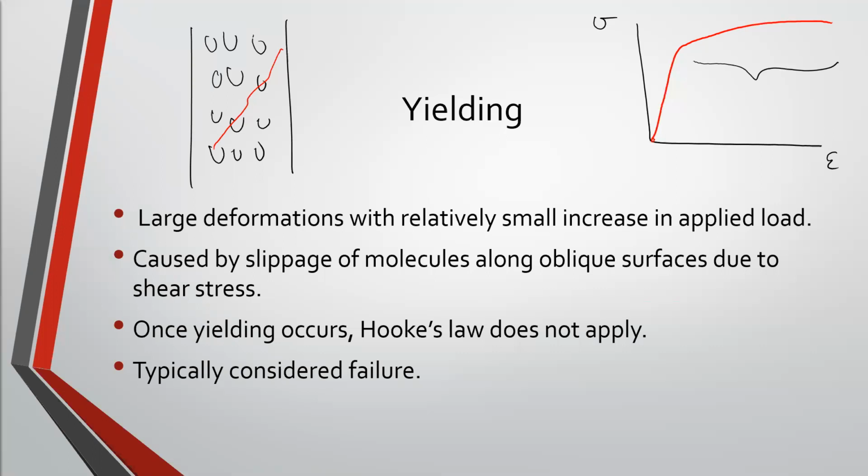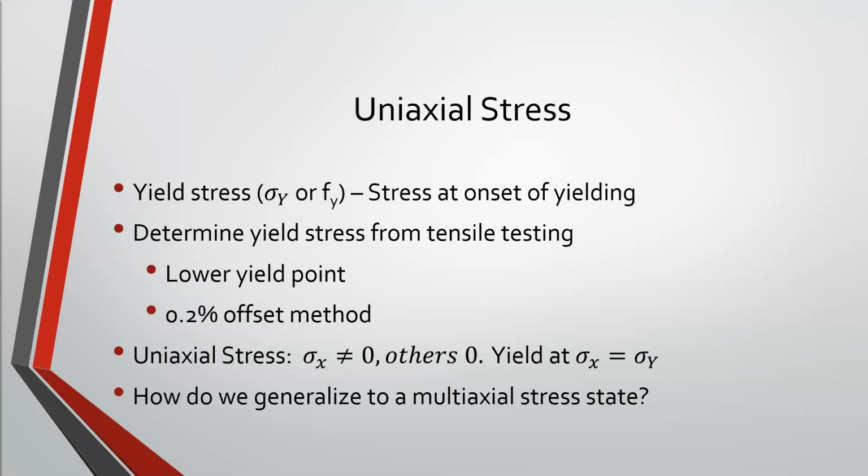So for example, for earthquake engineering, structural engineering, we do design portions of buildings to perform plastically, and we call that a fuse. So we expect that area to deform and elongate during an earthquake, allowing everything else to remain elastic and undamaged, and then we can come back in and just not retrofit, but repair that one particular fuse region. So we do utilize it, but by and large, we want things to remain elastic. So it's really important that we know when something is going to fail.